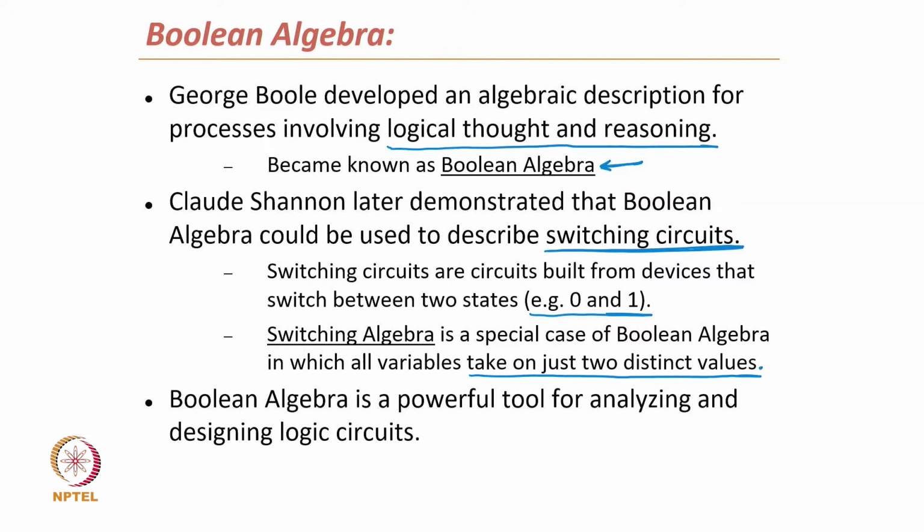So, in Boolean algebra we assume that the input and output take only two values, one is the low state 0 and one is the high state 1, and this is perfectly suitable for our switching devices, for example NMOS, PMOS and other logic gates, NAND and NOR gates, where the logic states are always 0 as low or 1 as high. So, we can apply Boolean algebra directly, and it is a powerful tool for analyzing and designing logic circuits. We perform this Boolean algebra all the time in designing digital circuits.